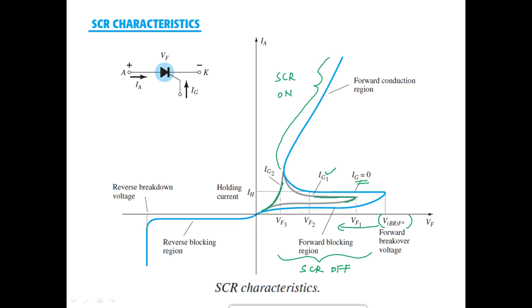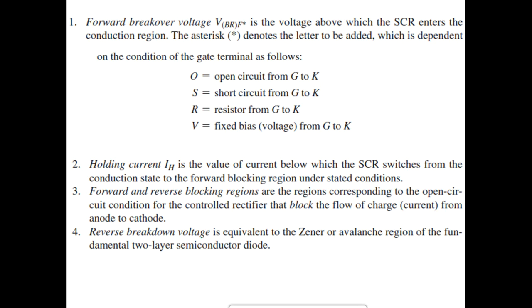If you further increase it, then you will get almost the same characteristics like this, right? So that is the importance of the holding current here. The latching current should have been mentioned, however; see, this is called IL, latching current, because it is beyond this stage that I can clearly say that the SCR has got switched on. Fine. Now in the reverse bias, it is similar to the characteristics of a normal diode. So you can just go through these points.